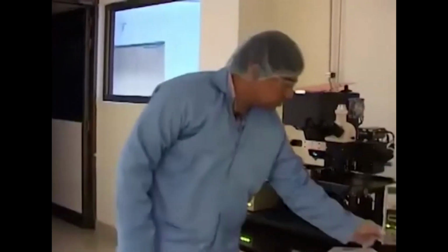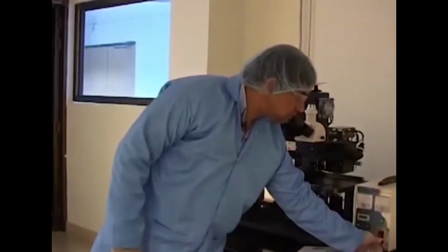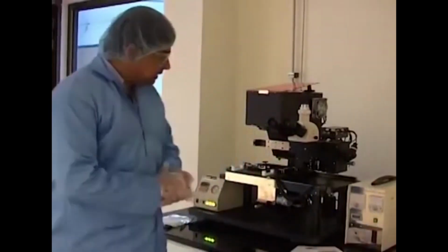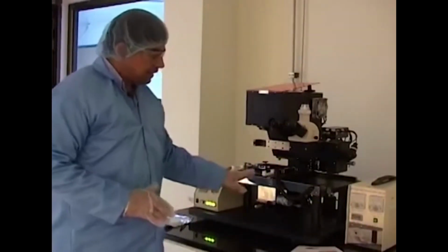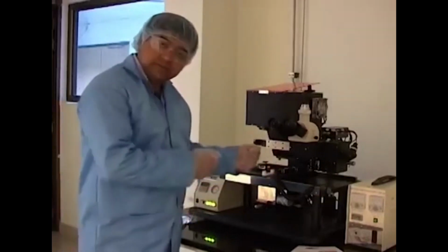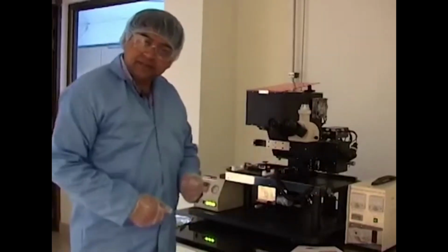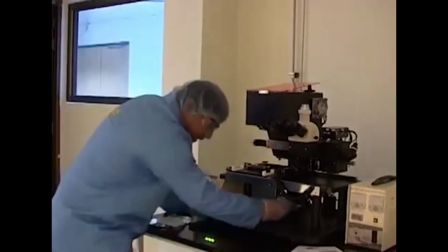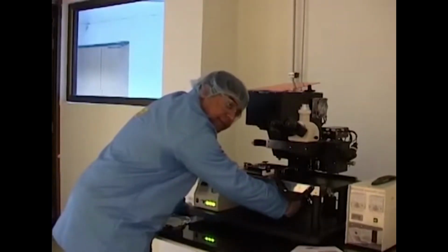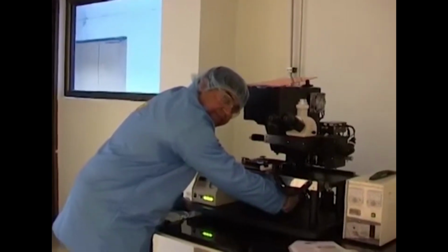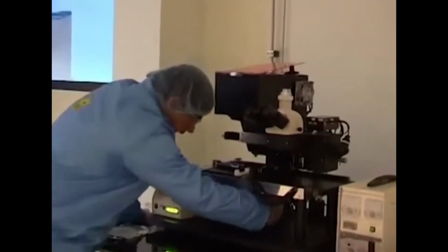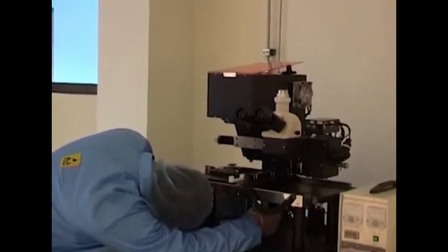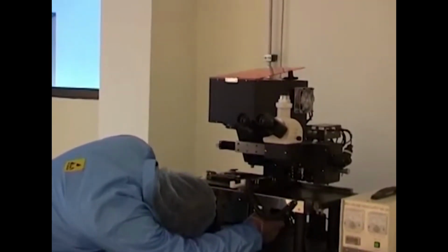Now I am going to turn off the exposure system, because it has been working for a very long time, and now we need to do the processing step by step, in a manner that we separate the wafer from the mask. A good way of doing that is to go anti-clockwise so that the masking stage can go down, and I can now take the wafer out, losing contact with the mask surface.